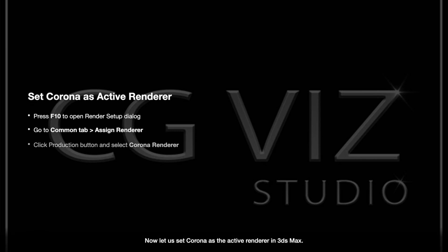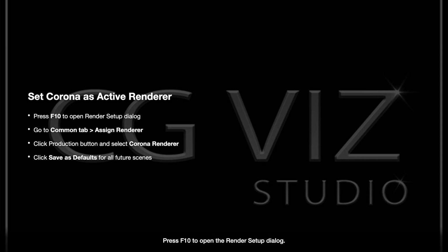Now let us set Corona as the active renderer in 3ds Max. Press F10 to open the Render Setup dialog. Under the Common tab, scroll down to Assign Renderer. Click the button next to Production and select Corona Renderer from the list. Click Save as Defaults if you want Corona to be your default renderer for all new scenes.